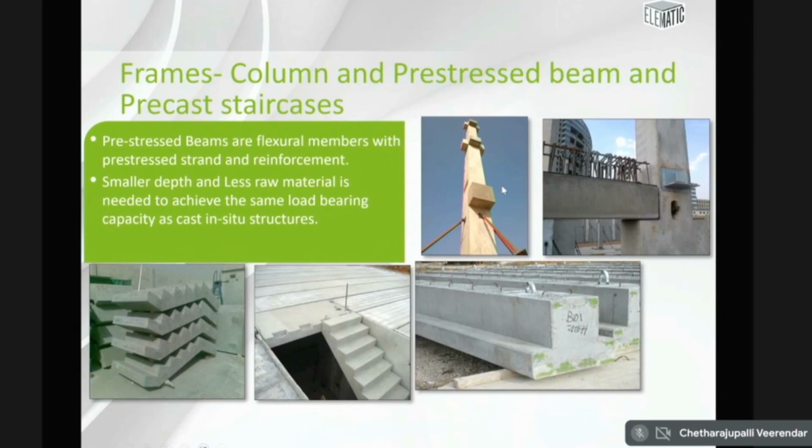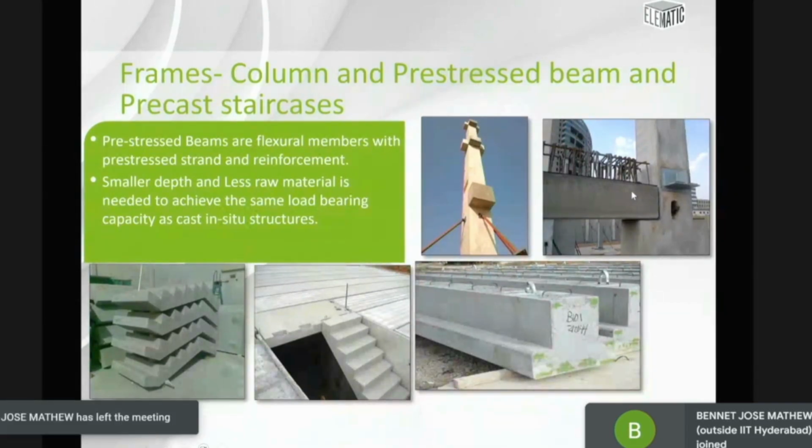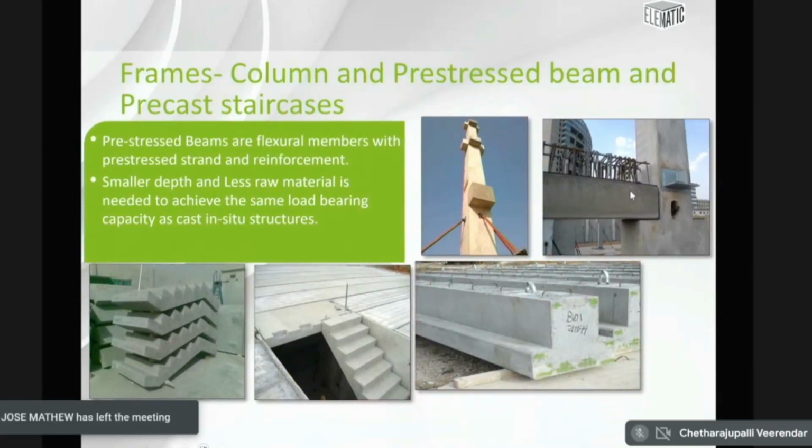It is produced in the stockyard by leaving some reinforcement, bent reinforcement ready, and then you make a secondary casting in the stockyard to produce the 4th corbel. You have also these beams. Either it could be a pre-stressed beam or a solid precast beam. Most of the industrial buildings do not require pre-stressing because they do not carry much load. Whereas in commercial buildings, we have this kind of beams having pre-stressing tendons plus reinforcement. Many of the projections are there for reinforcement. This will be merged with the slab when you do the site concreting.